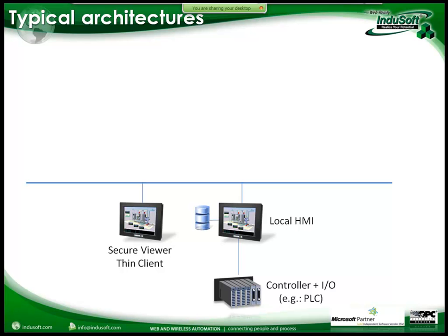So in each building they have a secure viewer thin client, but they just have one application running in one server collecting data from all the sensors. So InduSoft can run in this server station, collect data from many different buildings, many different sensors, save data to a central database, and then just provide visualization information to one or more thin clients via TCP/IP, via an Ethernet network.